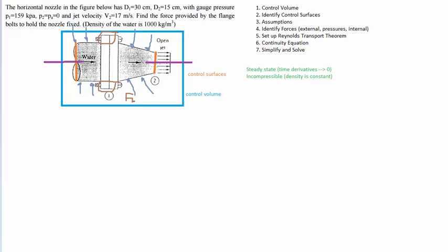The important part is that if you look at the top and bottom of this nozzle, all of these air particles are pressing up against it with the exact same force. The angle depends on the surface, but you can see that there is symmetry here. So we don't really need to worry about the pressure on the top and the bottom, or rather the sides, because we have to remember this is a cylindrical geometry.